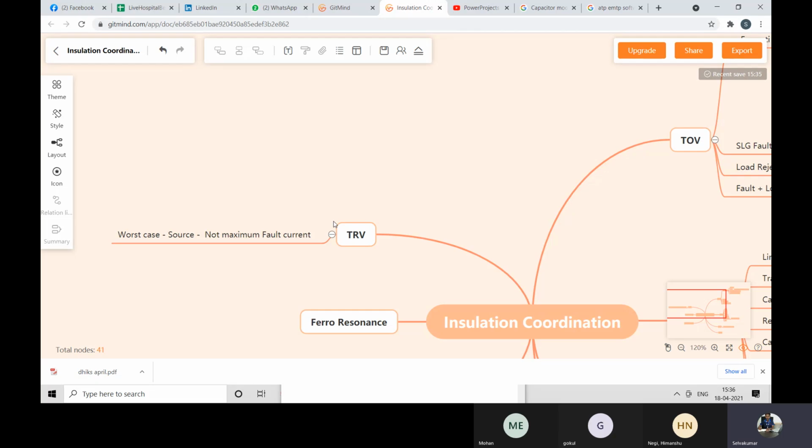So how do I visualize, what I am trying to say? If quite a lot of generators are connected, and only with the generator step up transformers, and not much length of a transmission line, then the fault current will be more. You got the point, no? We can easily relate impedance. So impedance is inversely proportional to the short circuit current, correct?